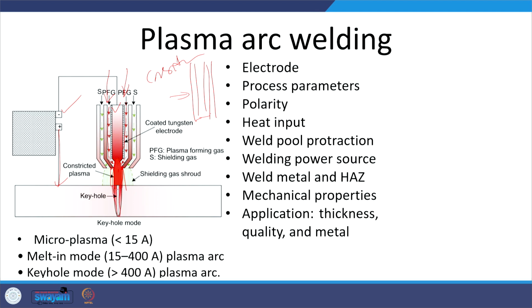So, here the weld pool will be produced, and at the center in the keyhole approach, when the current is high and the welding speed, the current density, and plasma velocity are proper, when all these three are maintained, we get a very stable keyhole. So, that allows the delivery of the heat up to the root, and that in turn permits the welding of thick sheets very effectively. Okay. So, if any of these, like the current, the power density, the speed of the welding, and the velocity of the plasma, are disturbed, then the keyhole collapses. Okay. And then our welding will become unstable, right.